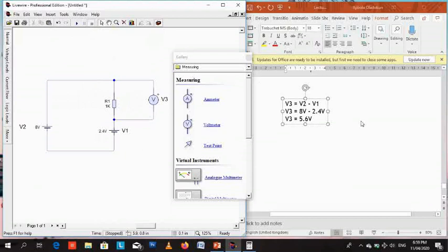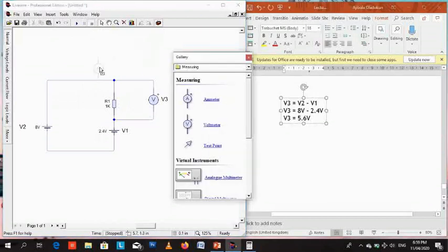It's trying to simulate that. So if this were a real experiment, you probably would have gotten a similar value. There's usually a little difference between the calculated value and measured value. In the calculated value, you are simulating an ideal case where there are no losses due to battery efficiency, internal resistance of the battery, things like that, or the cable you are using. You are assuming that there's no drop, that it's not a resistor, it's a pure conductor. So there's a little disparity, but in the ideal case it should be 5.6 volts.